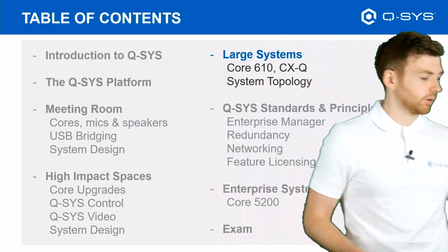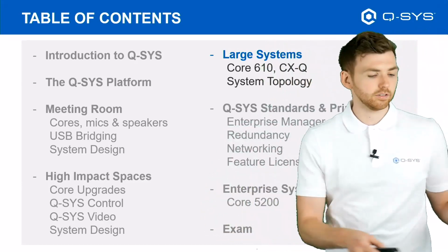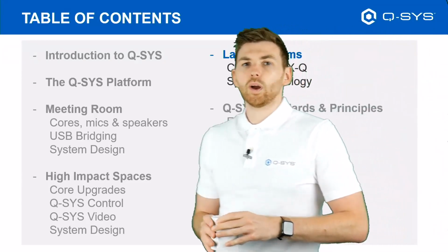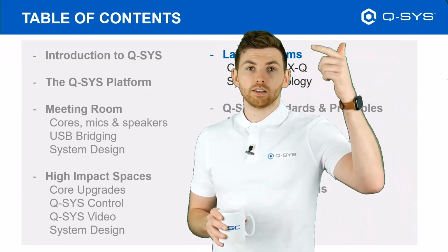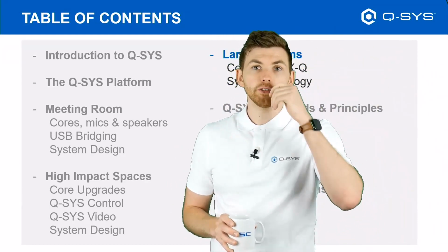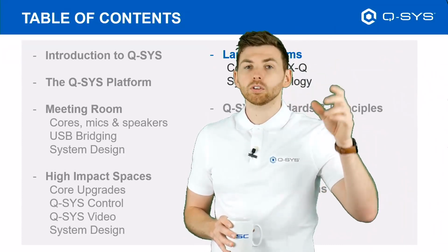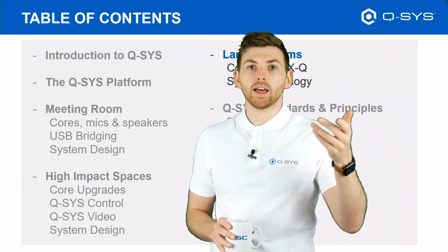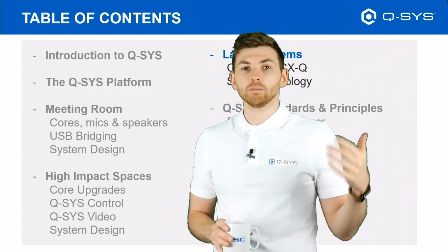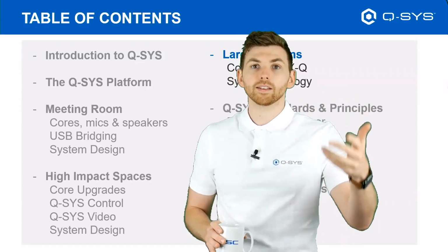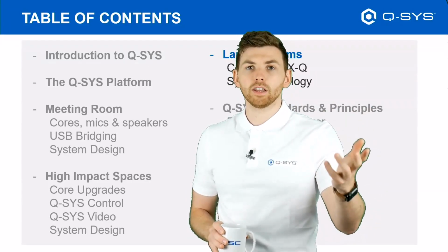Yeah, absolutely. So one of the nice things about these all being native Q-SYS devices is that inside Q-SYS Designer, you have this big block, which is like the NV32 and all of its sources and all of its displays, and the same for the NV21. And for every source, there's like a state that lights up or turns off when that is connected. So it actually monitors the 5-volt connection on the HDMI, or you can monitor when there's actually what we call valid format video coming through.